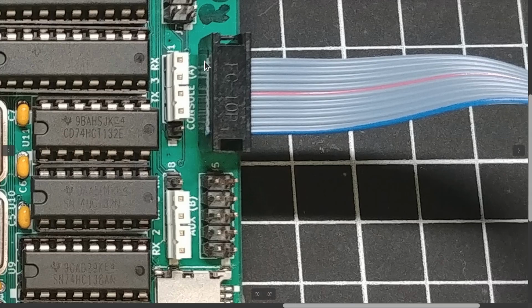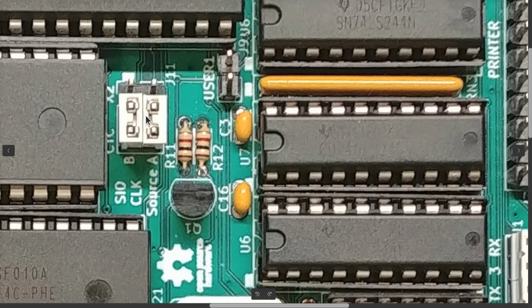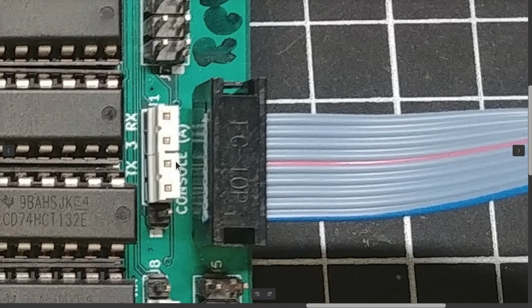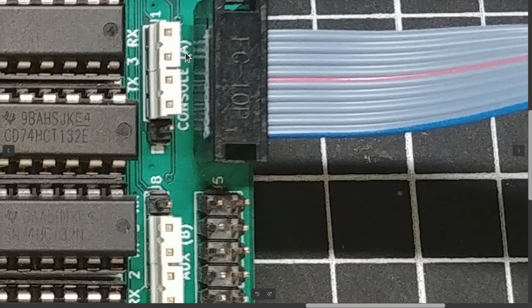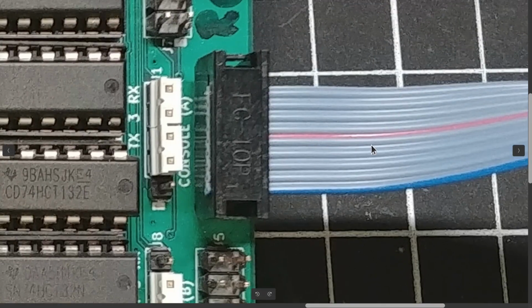They're not optional. The same can be said about the jumpers up here for this clock. You must have a jumper either connecting these two pins up here or, as shown, these two pins down here for each of the two channels. Otherwise, there's no clock going to the SIO. If you don't put any jumpers down here, on this jumper here or this one down here, then you don't have any of the data lines connected from this serial cable into the retro board.